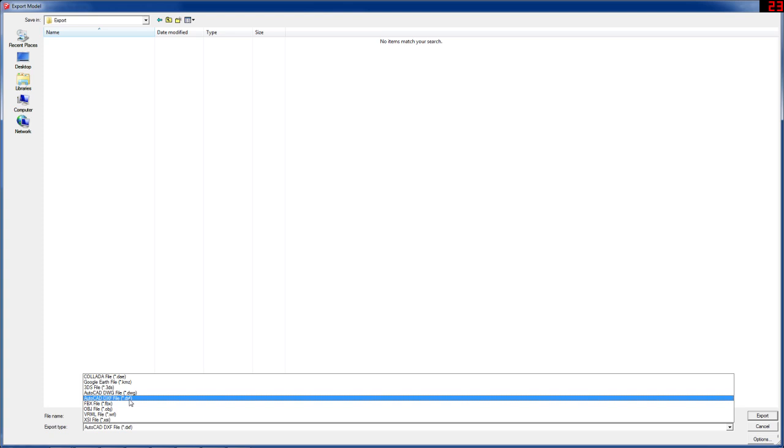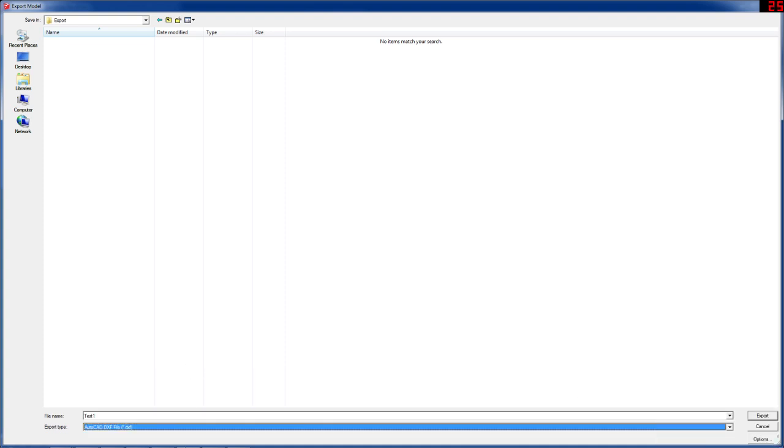Now, if the SketchUp that is being used at the university has a .obj or .3ds export option, use this instead, because this can be imported directly into Blender. The steps that we're taking at the moment is we're going to have to export it as a .dxf, then re-export that to an FBX, and then re-export that to an OBJ, which can be natively imported. So we've got a few steps of importation that are actually going to have to happen before we can get this over to Blender. So let's get started on that.